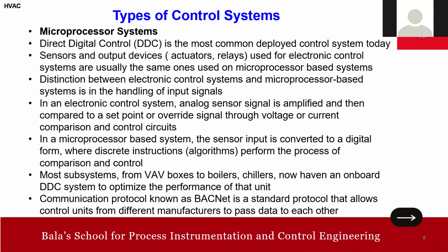Anyway, so now we are talking about the BACnet, right? Yes. So the BACnet, as I highlighted earlier, it is for interoperability and of course the data exchange and fault detection and diagnostics. So BACnet supports FDD, that is fault detection and diagnostics, which helps to identify abnormalities, optimize the energy usage, and detect potential fault before they cause significant problems. And remote access and control. With proper security measures, user can monitor, adjust, and troubleshoot HVAC devices parameters from a remote location.